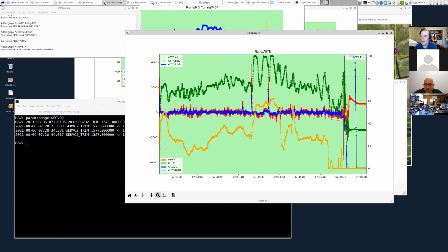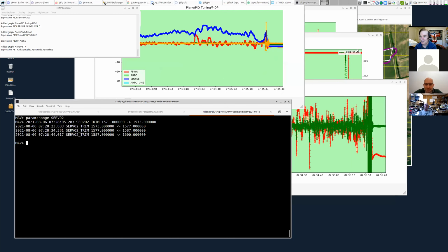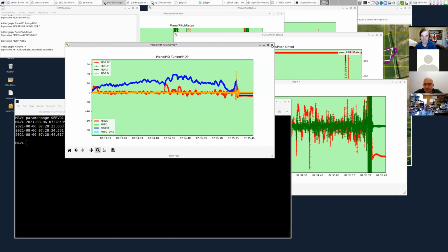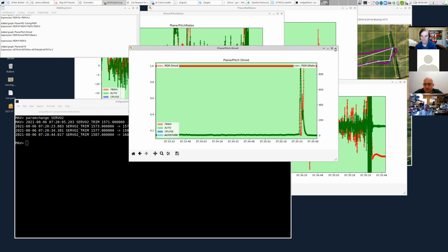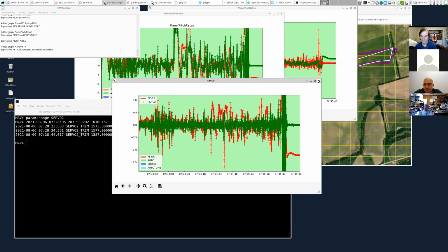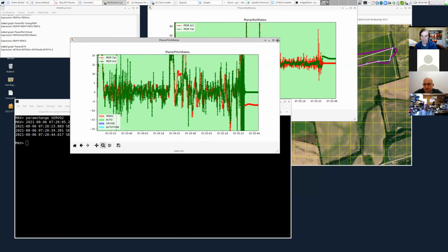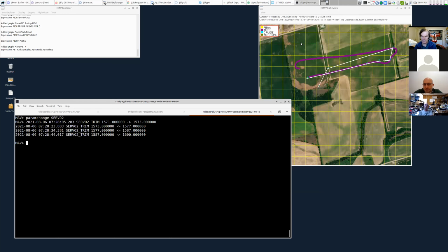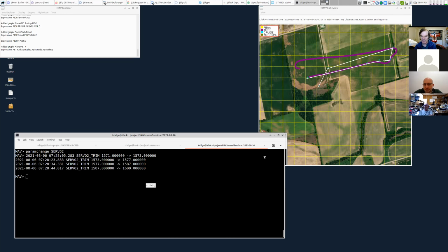All right, so I think it's time. Yep, Peter. Could the asymmetry you spotted earlier in the auto tune results be explained by being on the wrong spline, and thus also the integrator? Possibly. Yeah, I haven't really looked into the effect of the center of gravity being wrong on that asymmetry. I think that asymmetry is one.